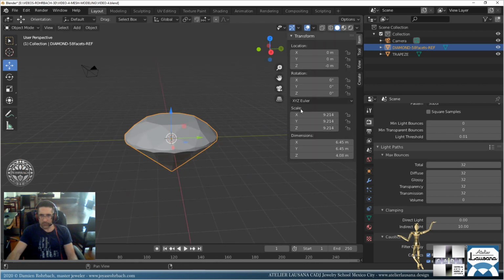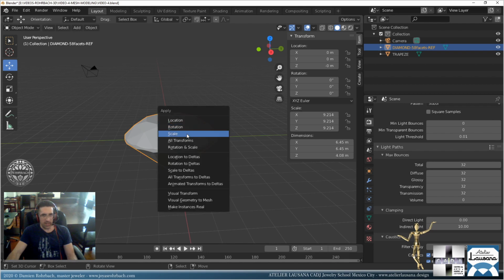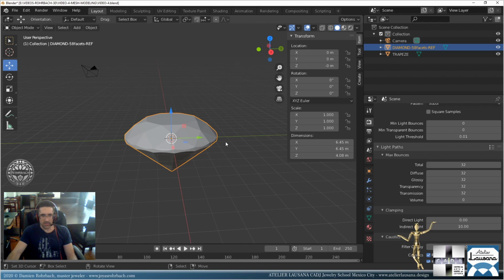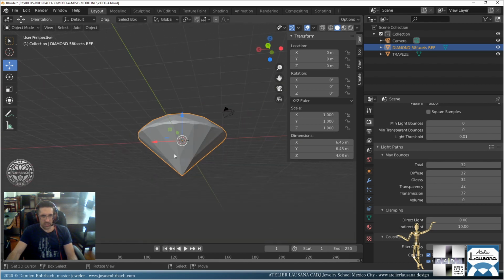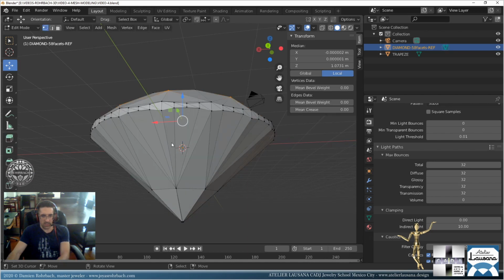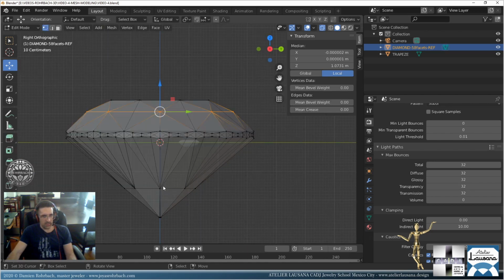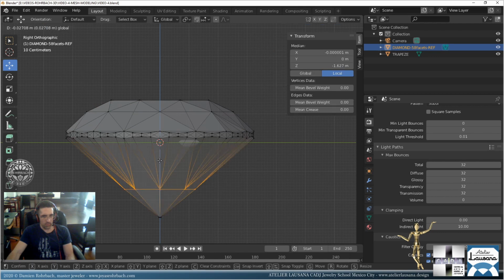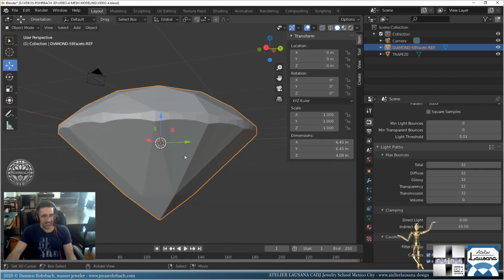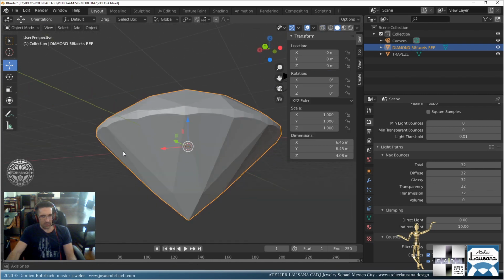That's the size of the diamond. In Blender, it's important to do a Control A and apply scale to have it set back to its origin. You know what? Now I'm checking on the downside. I'm also going to select those and move them a bit lower so the big faces don't look cut in half that much.